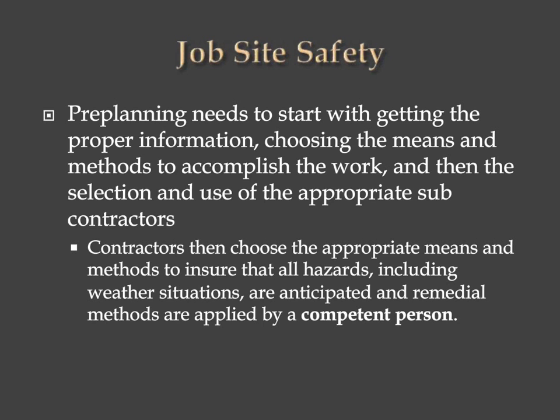And so what you need to do is to shut down for that particular day because of the weather conditions. Also, it doesn't give you a very good quality job when you're taking off shingles and putting up asphalt shingles, which are stiff and can break in that kind of environment. So it doesn't make any sense, not just safety sense, it doesn't make any economic sense, nothing. It's just somebody trying to hurry up a job and get it done without paying attention to consequences.